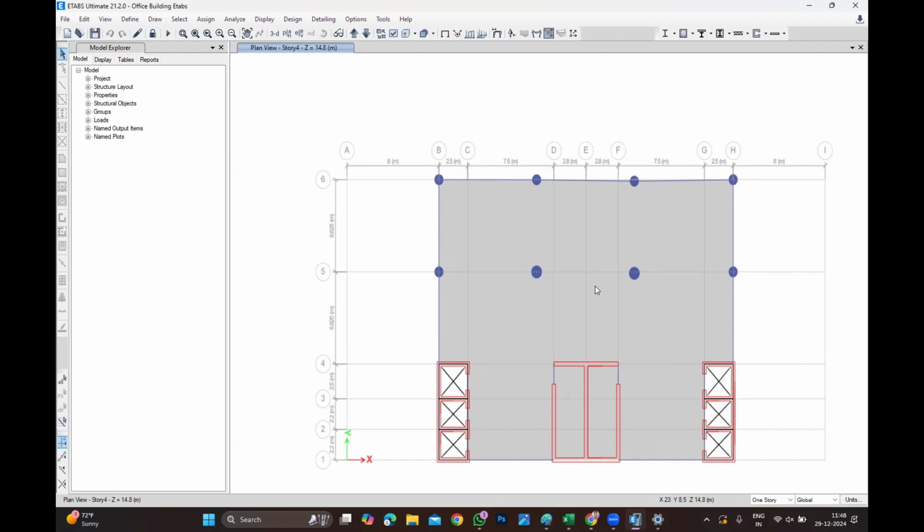This is a horizontal force. It is also called the shear force. Shear wall is what we take for lateral loading, for structural design. The other one is a normal core wall, just for a lift or something. Structurally, there is no word called core wall. When the boundary is closed, I can use the word core, but structurally it is all shear.